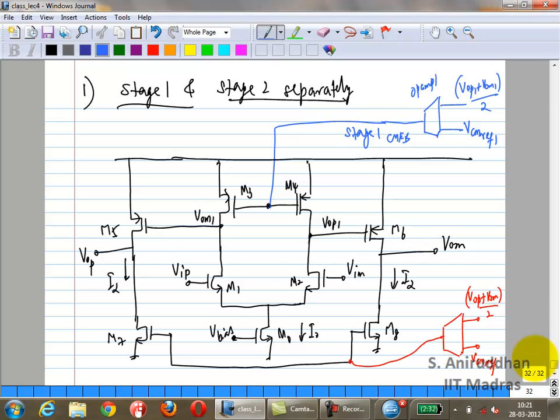We looked at this when we were looking at the single stage from the block level diagram. Everybody remembers that? Last month sometime we did it, right? For driving capacitive loads, this is fine. Even if it has a large enough output impedance, it's able to drive capacitive loads. It's only when driving resistive loads that the large output impedance becomes a problem. Correct?